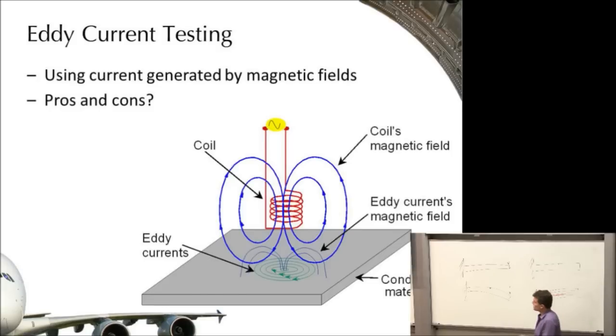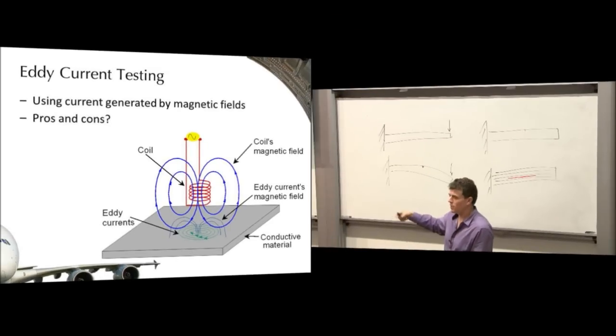Okay, eddy current testing is similar to magnetic field testing. You can detect changes in the eddy current set up in the material by defects. So an eddy current is a looping electric current set up by an oscillating field, and you can detect changes in that signature if there's a defect. Again, it requires a very skilled operator to use, because all sorts of different features will have different responses under this eddy current.